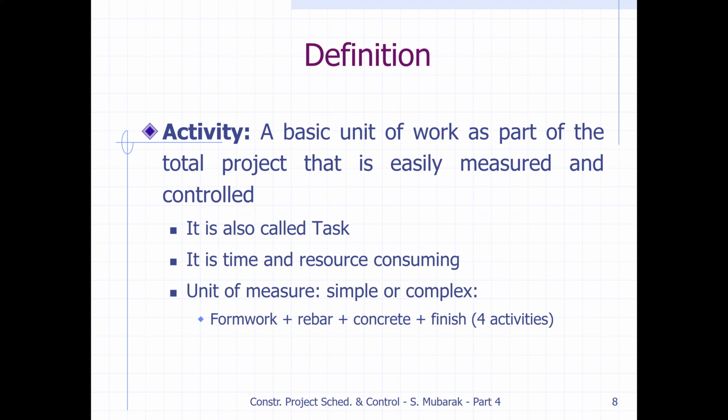Unit of measure. We need to decide what the unit of measure is. Formwork we can measure in square meters, rebar in kilograms or tons, and concrete in cubic meters or cubic yards. Take the foundation, for example.